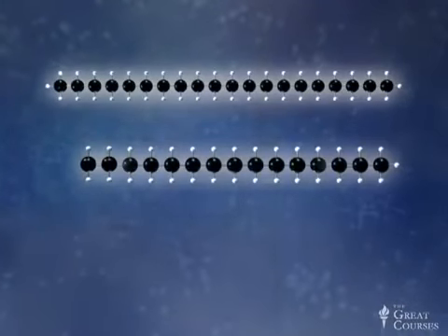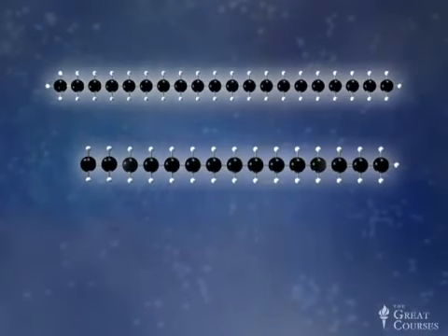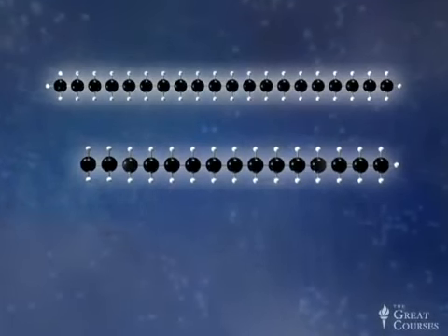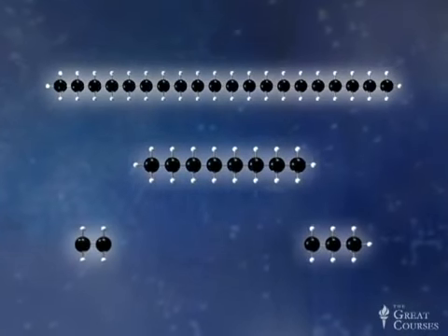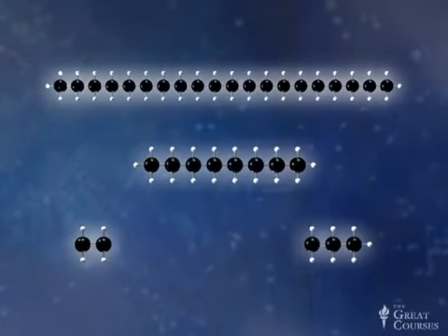So the role here of the zeolites comes in a couple of forms. What we're trying to do in the case of hydrocarbon cracking is to take what are typically the very long hydrocarbons. Think of diesel, for example, diesel fuel, but even longer, even heavier. And we're trying to break it down into the lighter hydrocarbons that we're more accustomed to using, for example, as petrol in our cars. We want to design our zeolite to give it the size and shape such that the reactions proceed to break these longer molecules down into lighter molecules, maybe 5 or 10 repeat units long, these shorter hydrocarbons, these more volatile hydrocarbons.